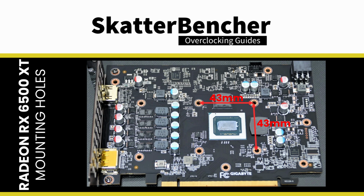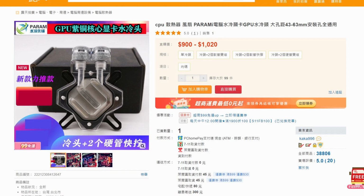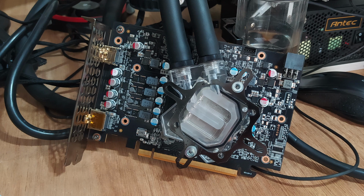In our final overclocking strategy, we slap on a water block and see if we get any better performance with cooler temperatures. The mounting holes on this graphics card are very close to each other, 43 by 43 mm, so finding a fitting water block was not easy. I eventually settled for a Parami universal GPU block I found locally here in Taiwan. It was still a bit of a hack job to fit the water block, but eventually everything worked.